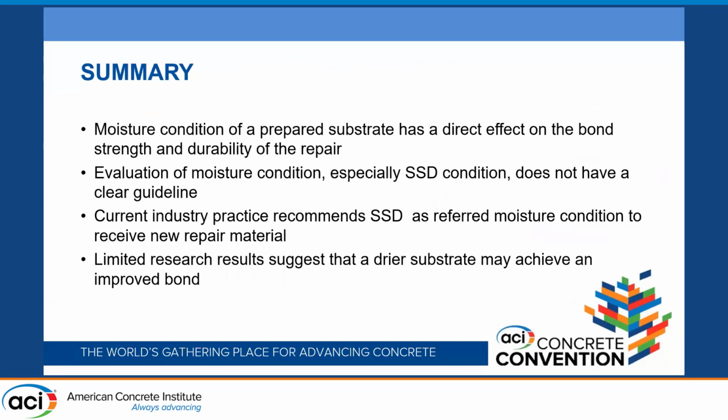To summarize what I just talked about in the last 15 minutes: the moisture condition has a direct effect on the bond strength and durability of repair. Evaluation of moisture condition, especially SSD condition, does not have a clear guideline. Current industrial practice recommends SSD as the preferred moisture condition to receive new repair material, and the limited research suggests that a drier surface may actually achieve an improved bond.